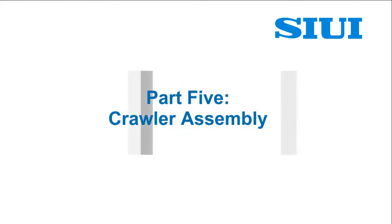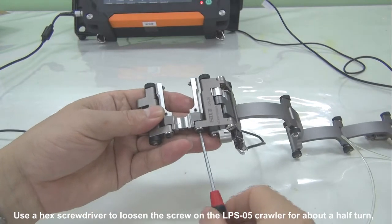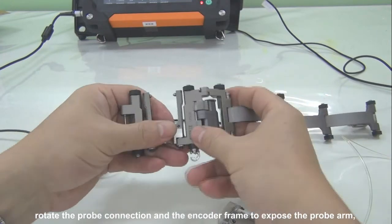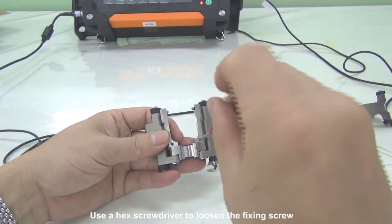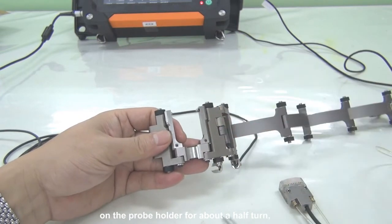Part 5. Crawler Assembly. Use the screwdriver to loosen the screw on the LPS-05 crawler for about half a turn. Rotate the probe connection and the encoder frame to expose the probe arm, so that it may travel outward. Use the screwdriver to loosen the fixing screw on the probe holder for about half a turn.